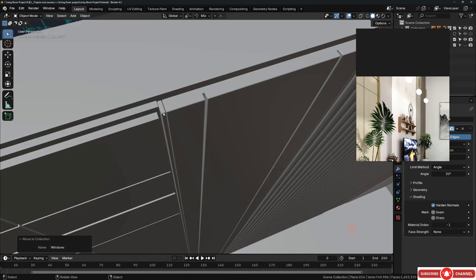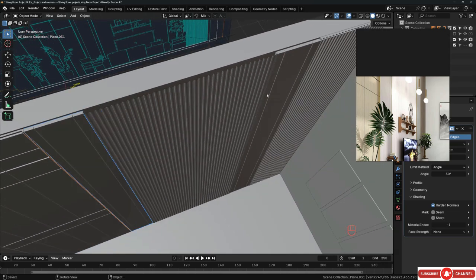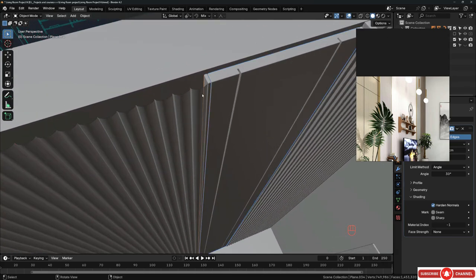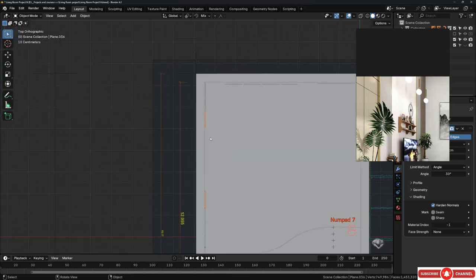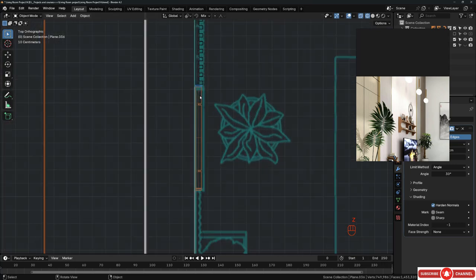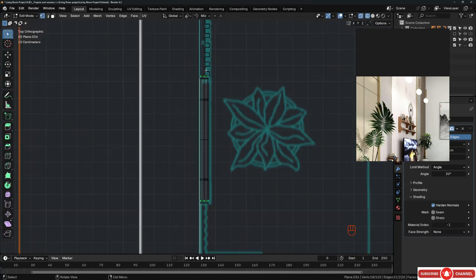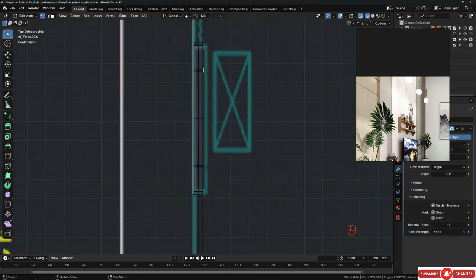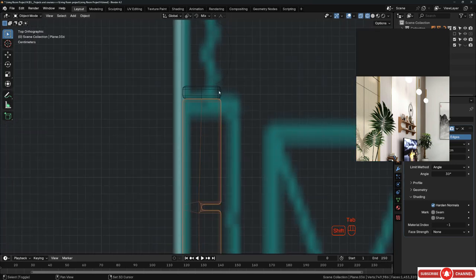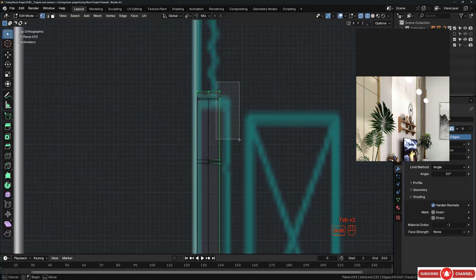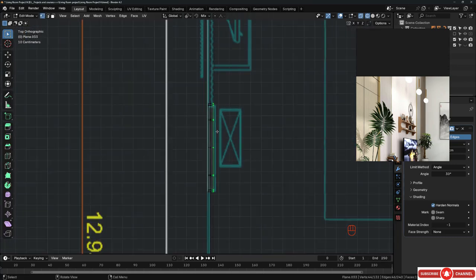All we should do is just grab these pieces like that and add these, and from the top you can go to the wireframe if you like and tap to go to the edit mode, and I will grab these vertices like that and go to this side, hold shift and add those as well like this. It seems like I forgot to pick this one, so I will tab out, hold shift to add this one, tab again, and I will deselect these.